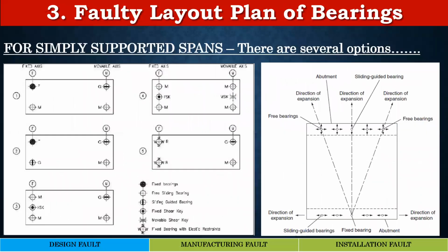Now let me come to the faulty layout plan of bearings, which could be one of the reasons for failure. There are several bearing layouts. Let me first start with the simply supported spans. There are several bearing layouts for simply supported spans which are in practice. Not all of them are, however, desirable ones, and some of them suffer from serious drawbacks. Unfortunately, we do not have any guidelines so far in IRC which guide the designer to choose a particular type of bearing layout, and it is all left to the ingenuity and the experience of the designer who is performing the design.